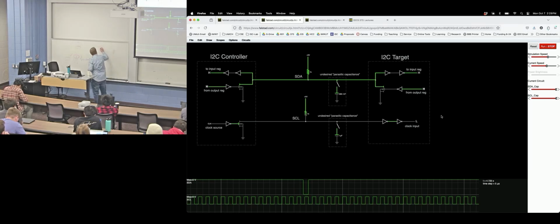So you're thinking there's, yeah, so you're saying this is a GPIO pin, right? And you're going to close the switch, so this is connected. And then what's the condition you're worried about? Like if our GPIO pin is going out to some trace that has really high capacitance or something, and has the potential to draw a lot of current when it's switching. Does that VDD from inside of our chip have a current limitation for the current coming into our GPIO pin through this resistor?